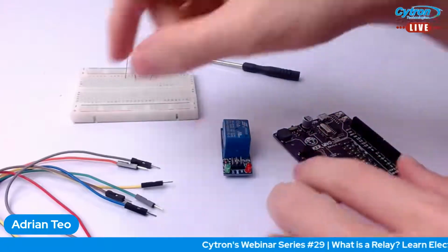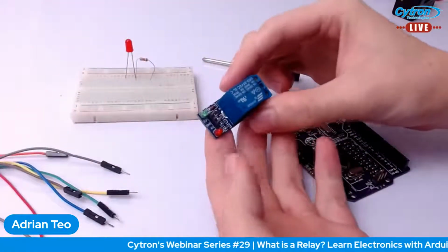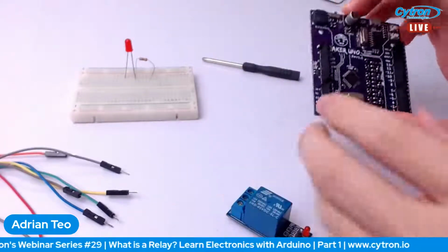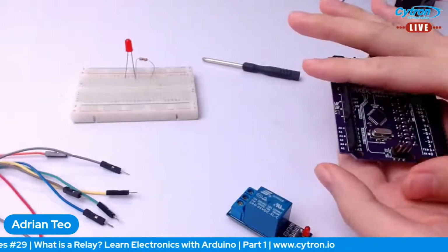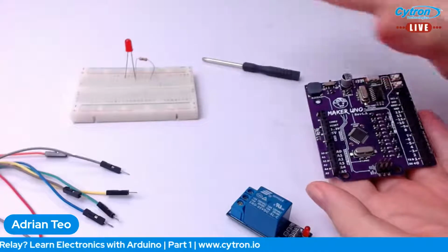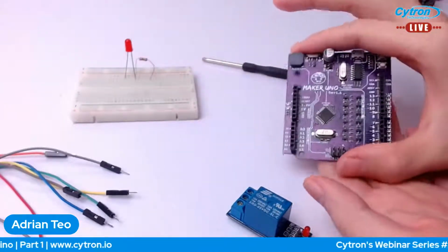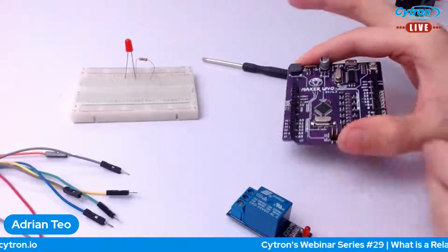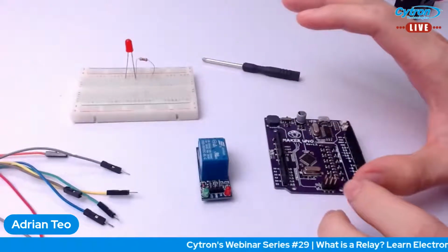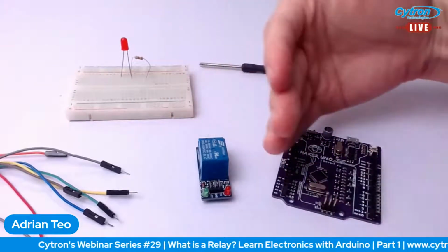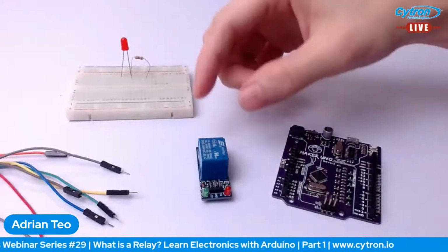So first things first, you will need to connect your relay. You are not going to connect the Maker Uno digital pin to your LED, because you're not going to power on the LED using any digital pins here, even though you can. Now you want to isolate these two. These are two different circuits: Maker Uno, and LED.